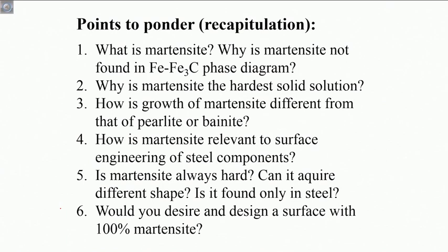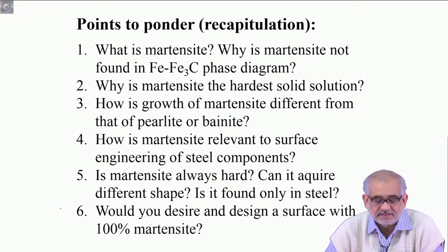We alluded briefly to various possibilities of martensite being non-hard or not as hard as in steel, and that's typically in the case of non-ferrous systems. And we also found out that martensitic transformation, or this shear type of transformation as a generic mode of transformation, is possible in very many systems, even in non-metals, solidified gas, ceramics, oxides, even in some polymers.